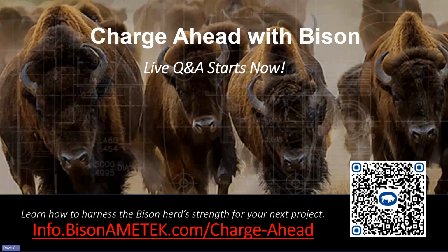Because if you use less amps, your amp hours get more hours, if that makes sense. So if we can make the motor more efficient so it draws less current and still gives you the performance that you need, then that should improve your battery life. And again, our more recent designs, our 6.6 and 8.4 low voltage versions, are quite good at this.